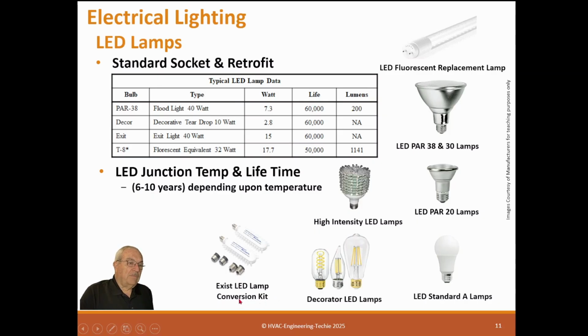Now, the one thing about exit lights, they originally had Christmas tree bulbs in there that were 20 watts, but two of them are 10 watts. You have four of them, and then you have 40 watts per fixture. Well, LED will be about 4 or 5 watts per fixture, so it's much less. Even though it's not a lot of watts, it's very significant. So when we do lighting for retrofits, we always change to the